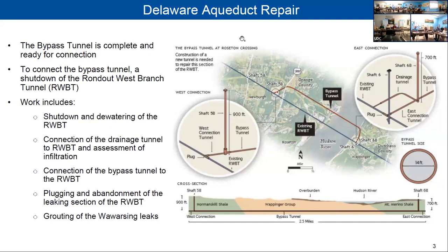That will increase the flows out of the reservoirs into the river, because when you do this, the water has to go someplace, right? Right, but it's not like the one coming in October of next year, which is going to be shut down for months. So we don't have to create that large void in the reservoir. Next year, when you totally dewater it, then we'll start to draw them down. But because this is a short time period, we can operate normally to the FFMP. And if we creep above the CSSO, we have discharge mitigation releases that we can make to bring it back down.